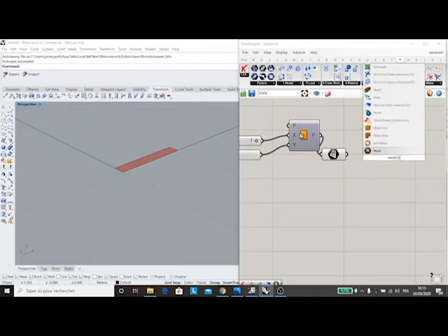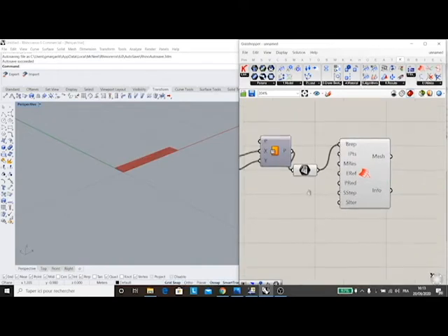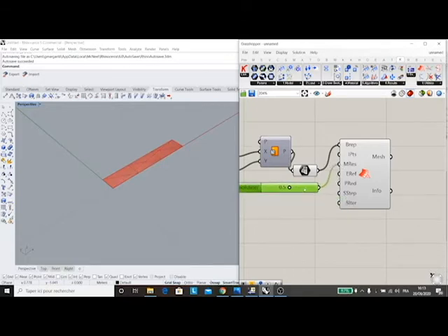and mesh it using the component of Karamba that is pretty good. I have to adapt the resolution of the mesh so that I have a good discretization for the length and the dimensions that I have. So let's keep it like this. And you can also change these parameters and make it smoother. It's in general important to have same length edges for the structural analysis.